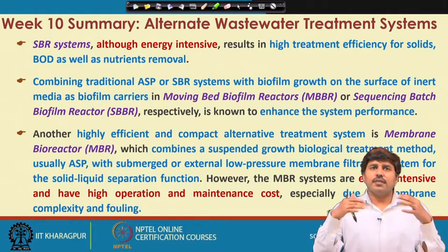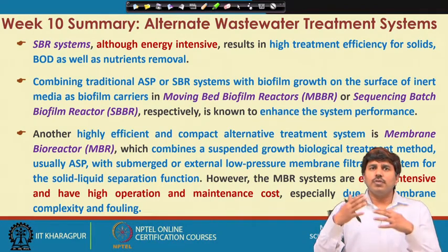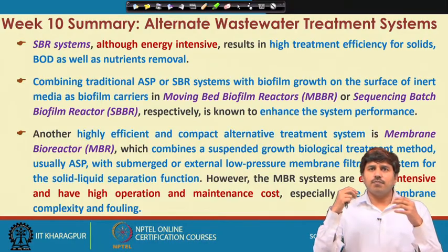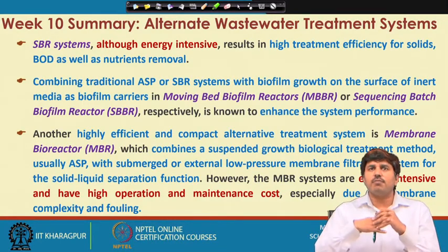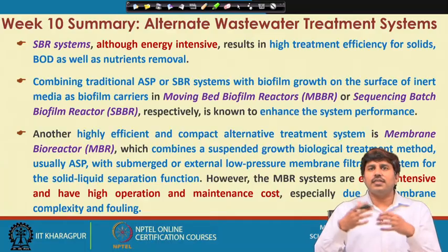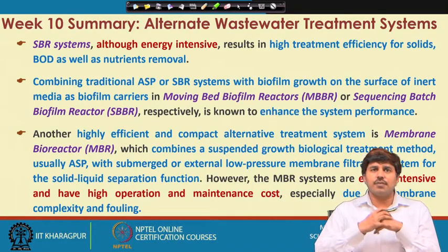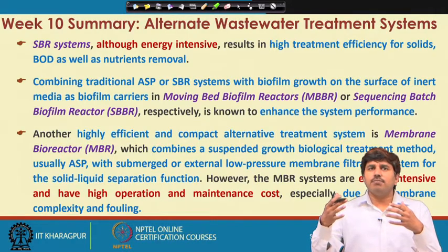Then either the conventional activated sludge process or SBR systems could be augmented with biofilm carriers, and then biomass growth takes place on the surface of these inert media, which act as a biofilm carrier. So, we get the advantages of both suspended as well as attached growth systems. These are done in moving bed biofilm reactors, which is MBBR.